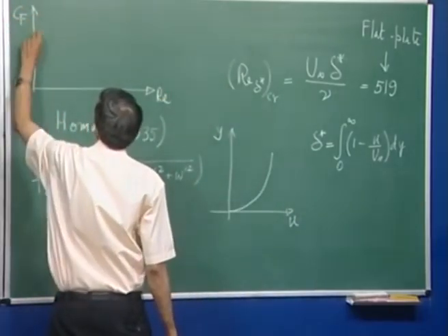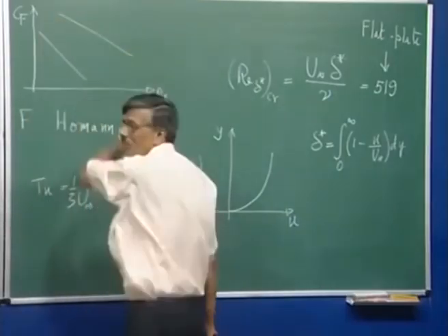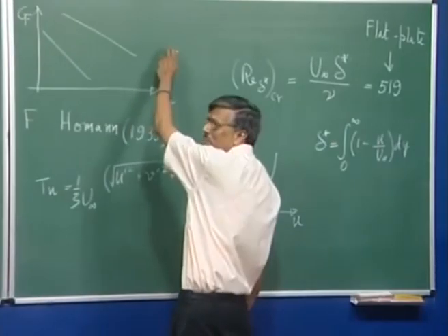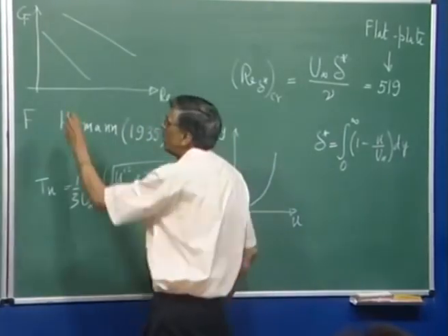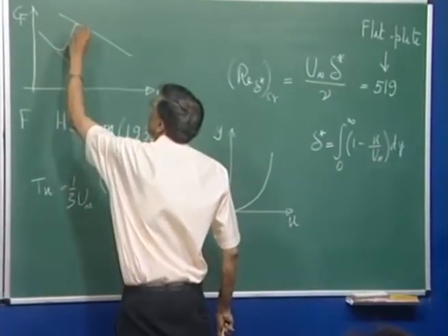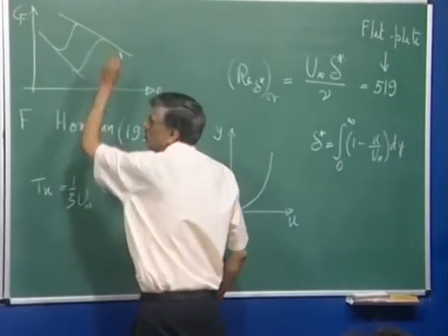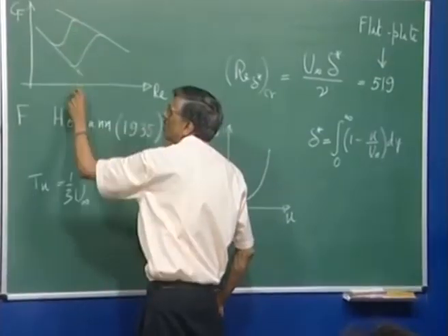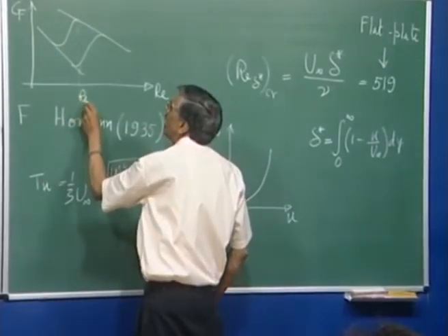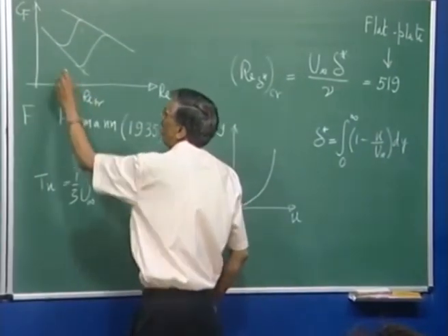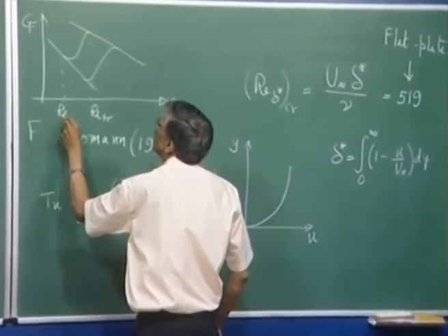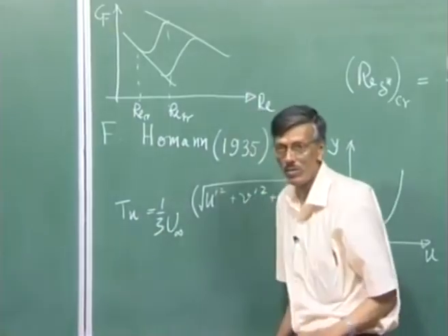If you recall, we had this. This is the laminar branch of the solution, this is the fully turbulent branch of the solution. Depending on disturbances, you could go like this or you could go like this, and so on and so forth. So, that is why this is what I will call Re transition, and this I will call, let us say, Re critical.